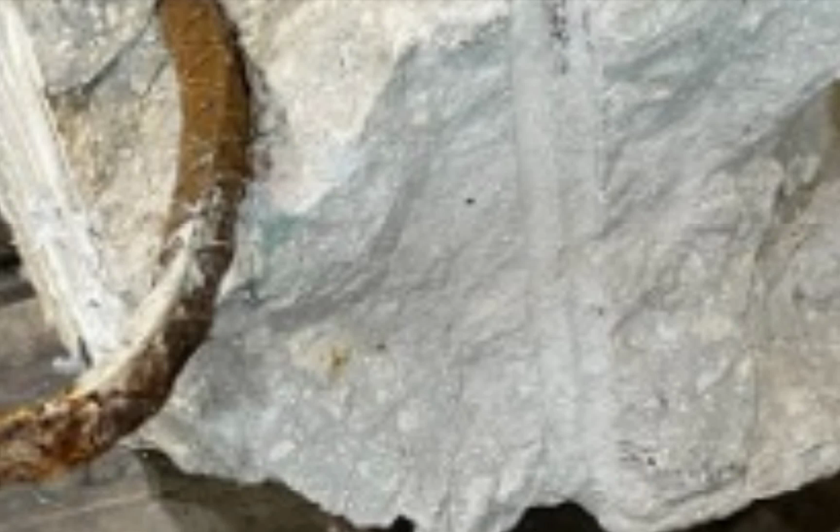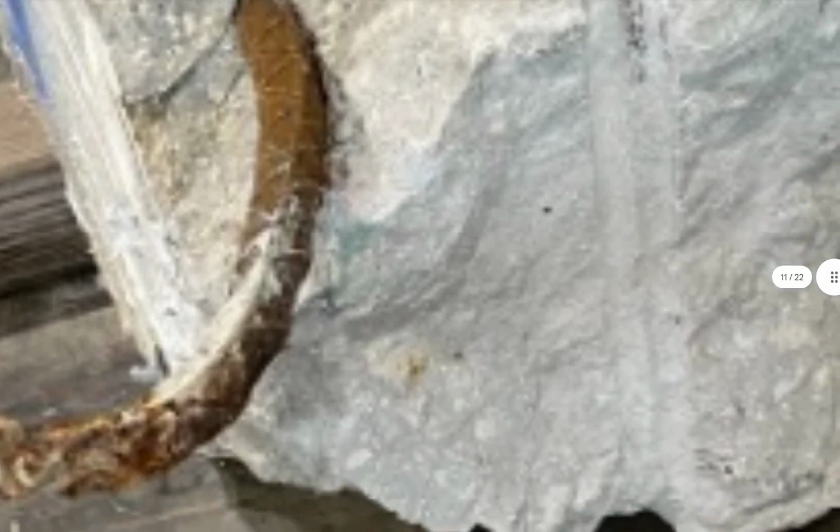I'd be able to tell you how much of it deteriorated, but how much was put there intentionally initially. What it tells you is that even over these years, whatever this photograph was taken, you do not see rust around here. So that bar was not rusting. Those bars weren't rusting. It didn't create any rust stains. As we look to the left, this bar with the rust on it created no rust stains. So there was no water penetration at that location causing that. I would say no water penetration over all those years. It would have stained that concrete significantly. I would give it a 0 on that.